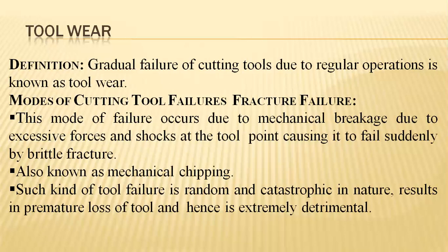See here, the similar load which is applied repeatedly, considering our lathe machine, which is holding the object that needs to be machined for better dimensional achievement, and MRR, material removal, has to be considered over the material with the help of this tool. So the coefficient of friction will be developed. The rotation of this spindle will be considered per minute. Based on the rotations, the feed and depth of cut will be induced by the tool over the material. This is a continuous, repetitive process acting on the material for eliminating the excess material in the form of chips, or an amorphous state or tiny particles, which have irregular shapes.